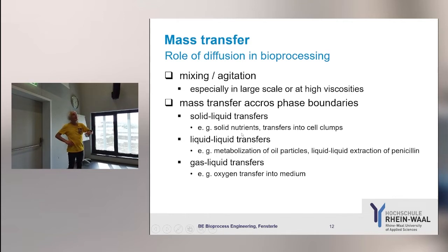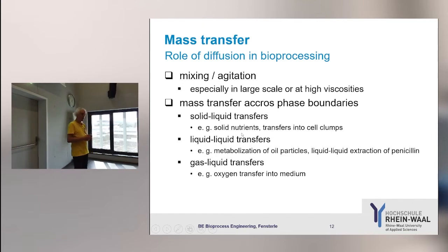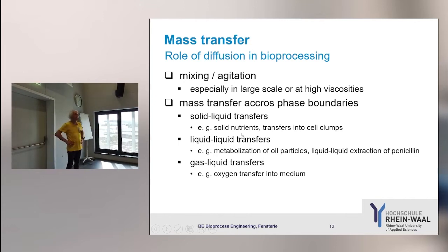So this takes way longer to have the complete exchange of the air. If you took a shower in the bathroom, for example, and the temperature of your bathroom and the outside is the same, just the humidity is different, and no air gets in and out, then it takes long to get this humidity out. If there is a temperature difference, you will always generate convection because there will be an air flow. But if it's assumed the same temperature, but it's windy, then you just blow in the other air and that's way faster. So that's the difference between convection and diffusion, and diffusion takes longer.